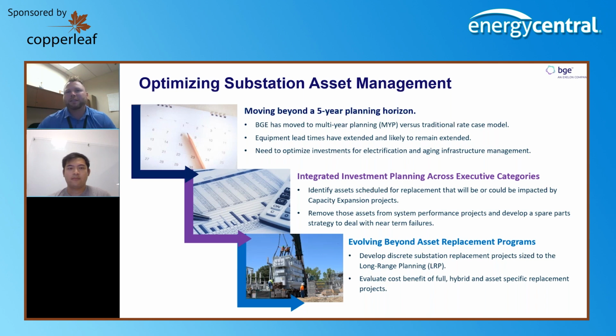And we're starting to see things where I'll take a transformer as a good example. If you're replacing a transformer, you might also find out, hey, all the control cable at that substation's bad, as well as the circuit switchers, right, and breakers and the disconnect switches. And so your transformer replacement might increase in scope to the point where you've done a project that's quite larger than what you intended to do in an individual asset replacement program.